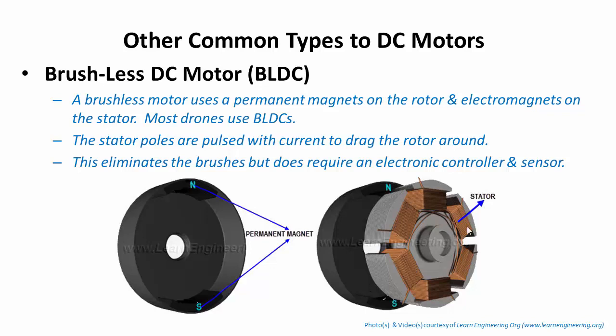Within here, you have coils of wire around some ferromagnetic material such as iron, and if you turn it on, it creates a pole, which could be a north pole or a south pole depending on the direction of your current. So if you had a south pole right here, and you stuck this inside your rotor, the part that's moving, you could pull that north pole over here, and it spins over to the north pole.